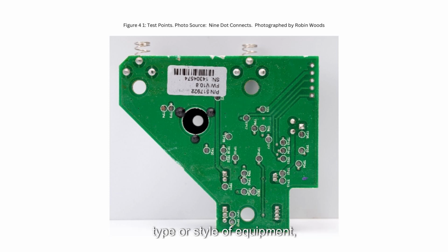Regardless of the type or style of equipment, there is a physical connection that must be made to exposed metal of the board. This contact can be exposed copper on the board, such as test points, the solder surrounding the leads themselves, or the pins of the connectors. Note, placing any probes on the leads themselves is not advised, due to the ease of bending and/or shorting a lead to another. In addition to spatial accommodations of the components on the board, the designer should consider the use